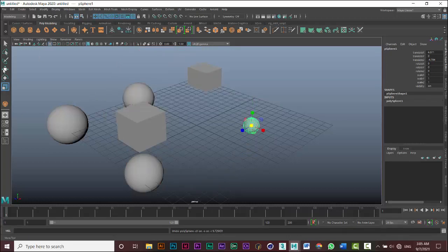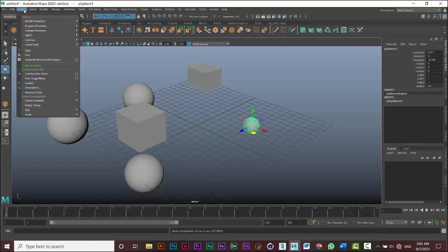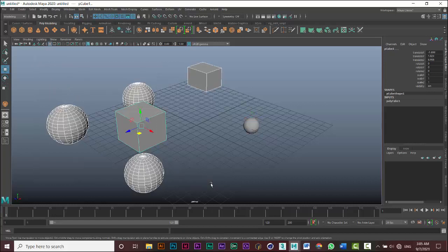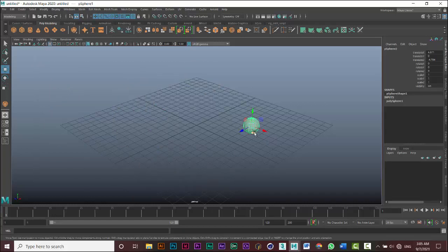All right, so for now I'll just leave it on, doesn't matter. So I want to talk about the channel box. So I come back in here. All right, so I have the translate, and I can zero out the points just by dragging left with my left mouse all over them, then turn them all to 0 so that it's lined up.